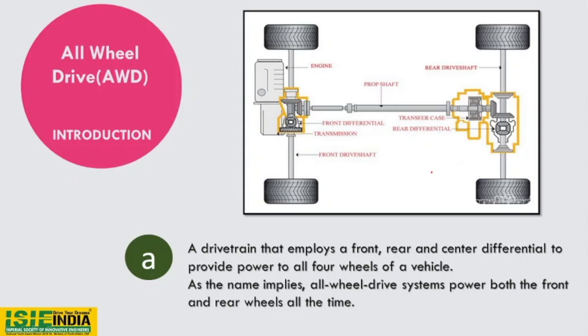It is operated most of the time in two-wheel drive mode, with power being delivered to all four corners only when additional traction is needed. It is all controlled electronically, that is the transferring of power to the respective wheels. There is no manual connection here. All is done with the help of the ECU.